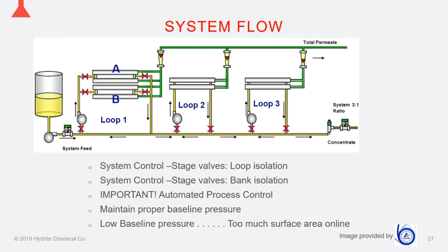So what we do is we would start with bringing on loop 3. We would start backwards, bringing on loop 3. The reason for that is our membrane system, when it's shut down after CIP, is sitting in water. If we were to start from the front end to the back end, as we brought on all those other loops, we would be diluting that concentrated 15% because we would be introducing water as we go through.